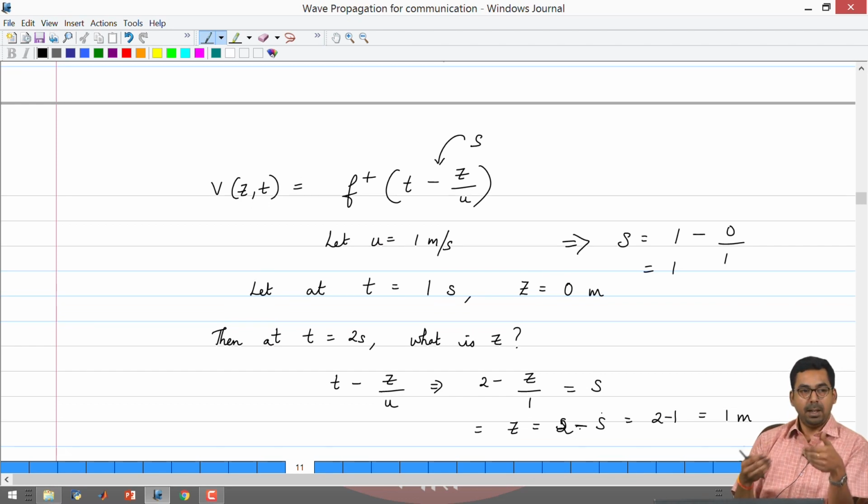But in realistic conditions, you are going to have finite length transmission lines with terminations or load resistors which are not going to be matched in some aspects. Then it triggers a backward wave, and at any given point of time you will be measuring the sum of the forward and the backward wave, okay. What that means in terms of system design is something electrical engineers will need to worry about, all right.